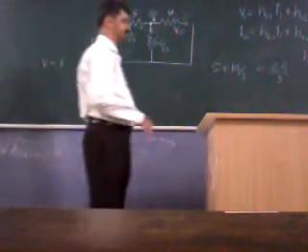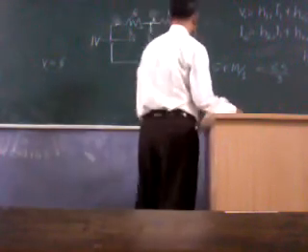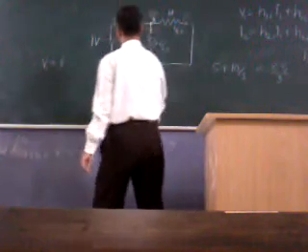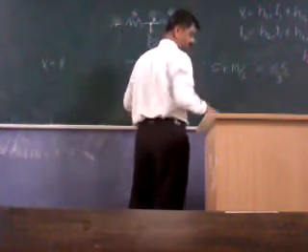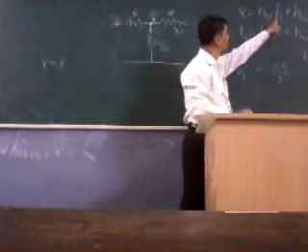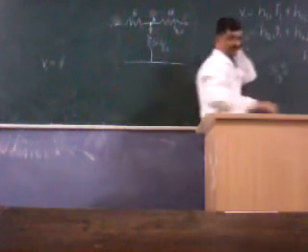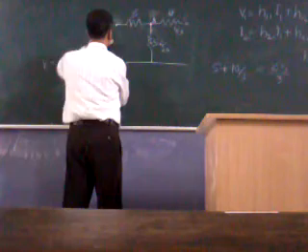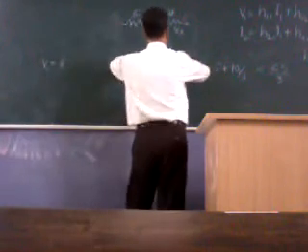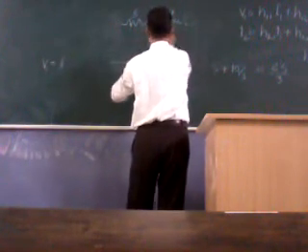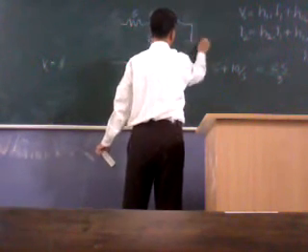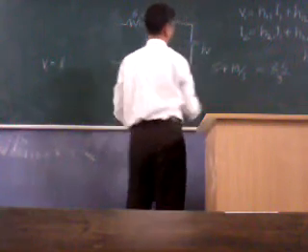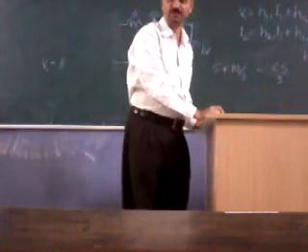And next, to find H12 and H22, for that, port 1 should be kept open. So don't connect anything in here. But connect 1 volt here. What is V2? 1 volt.